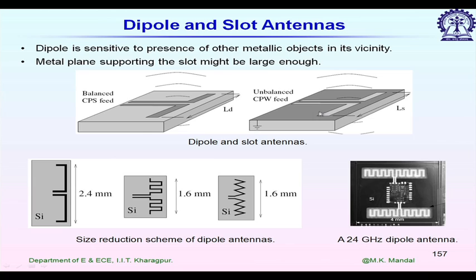This is the second example. This is a complementary dipole structure. This dark part is showing the metallization, whereas the feeding line is the CPW line, the slot, and you can see the dipole. It looks like a dipole, but the arms are basically etched slots in the ground plane of this antenna. It can also radiate, it has complementary properties.